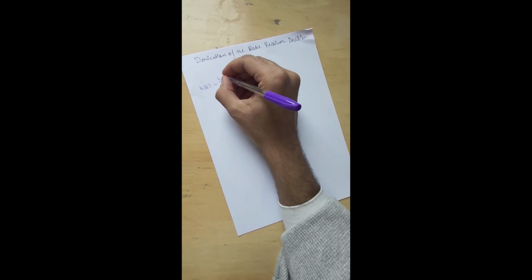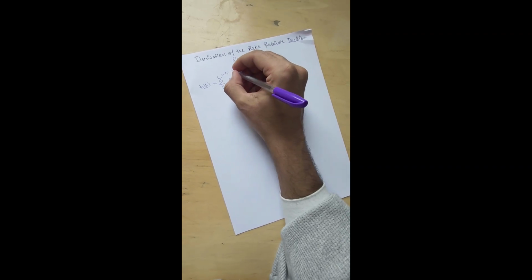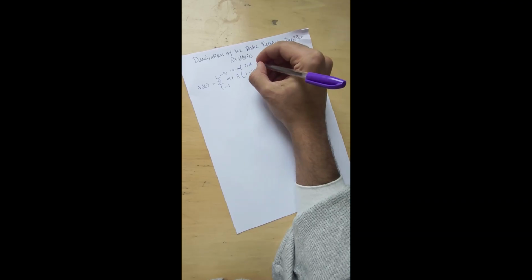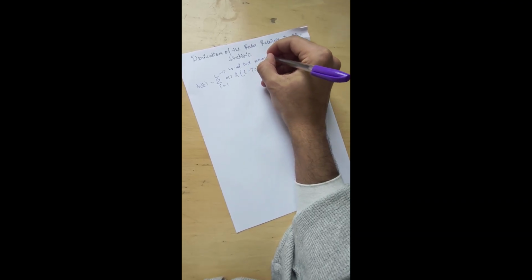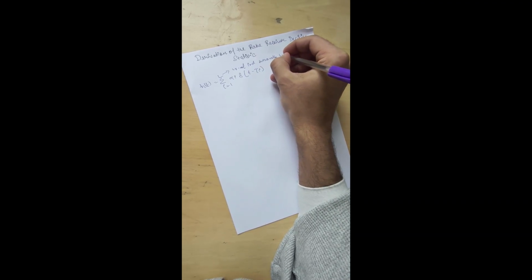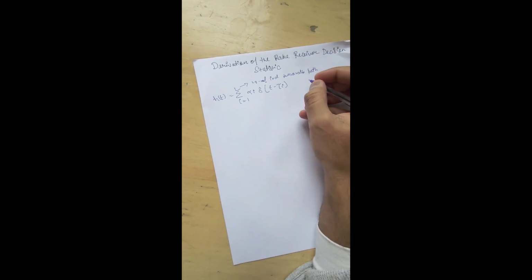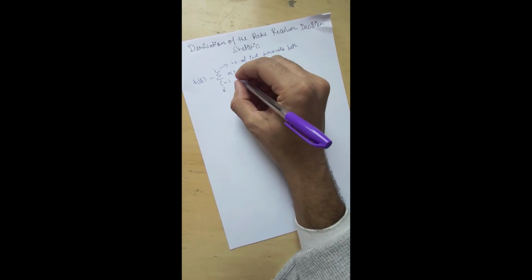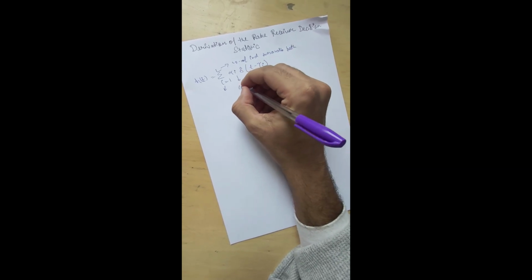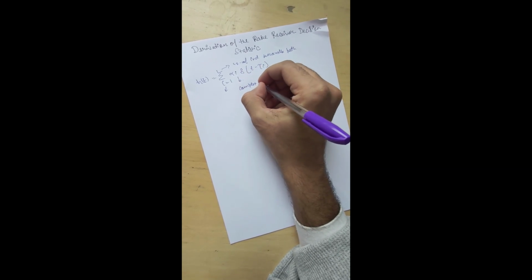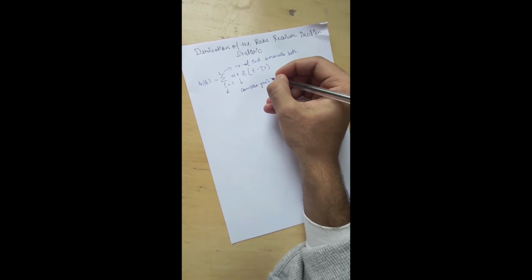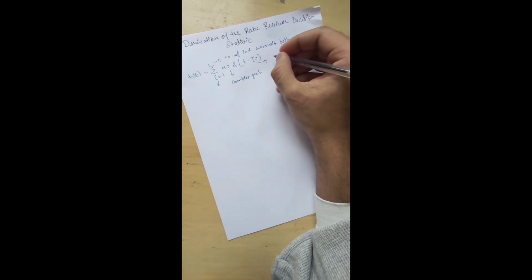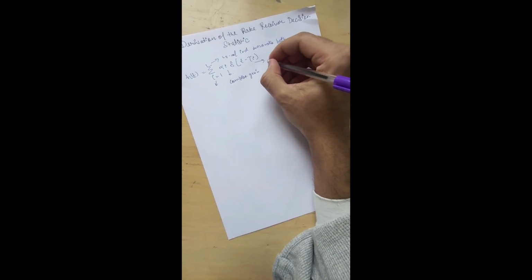Here L represents the number of independent resolvable paths, and for each component i, we have a complex gain alpha_i, which accounts for fading, and a delay associated with each component represented by tau_i.